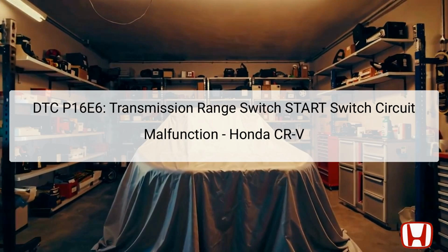The Honda CR-V models from 2017 to 2022 can exhibit various diagnostic trouble codes, DTCs, with DTC P16E6 specifically indicating a malfunction in the transmission range switch start switch circuit. This error can arise from several issues, including wiring faults or problems with the transmission range switch itself.